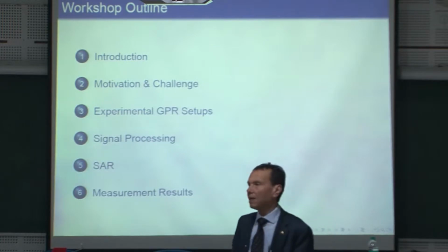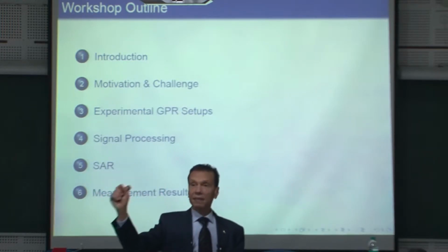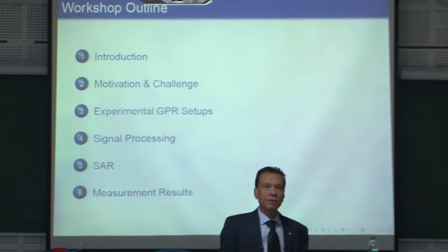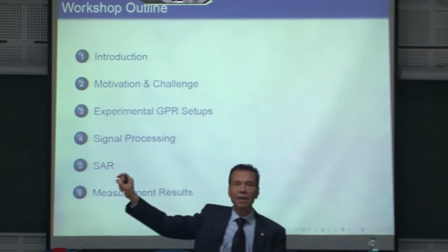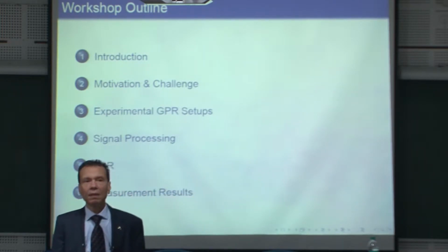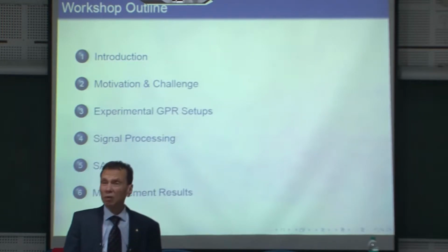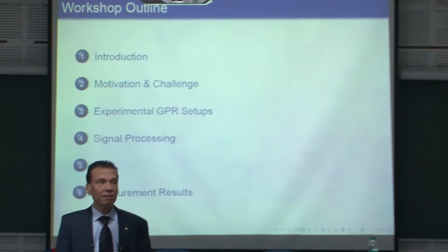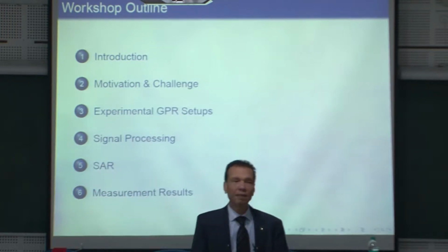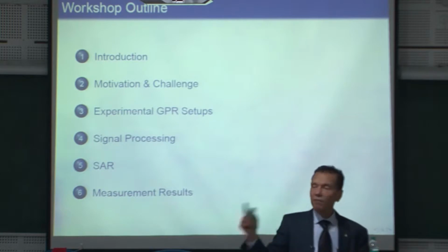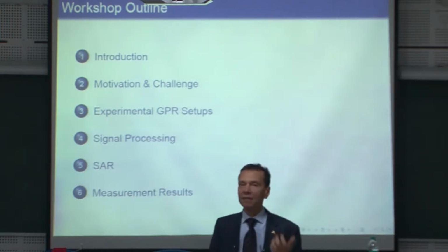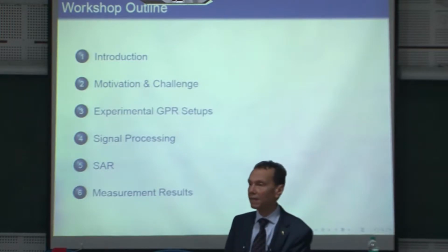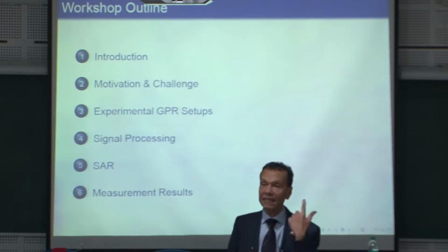Because what is an antenna array? I have individual antennas placed statically at certain points. The question now, why not have only one antenna, and I will move it. I will have a measurement here, okay? And if everything is periodic, because I work monochromatic, I will measure the next period here, the next period there, and I go back and forth in 2 dimensions as wide as I wish. Therefore, this is actually synthetic. Synthetic aperture, the aperture itself is not physical. This is actually created by moving a single antenna.